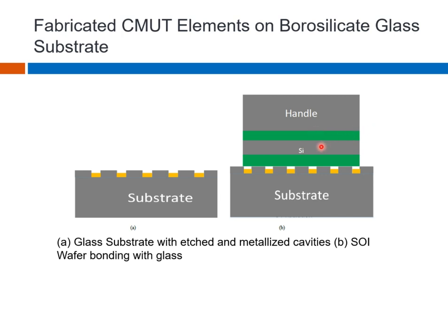We had about 700 microns thick handle, which was removed by RIE, and the SF6 gas stops etching silicon when the buried oxide layer is reached. That layer is removed chemically with buffered oxide etching, and you're left with a device silicon thickness of, let's say, 40 microns, and a passivation film just to avoid any shorting of the two electrodes.